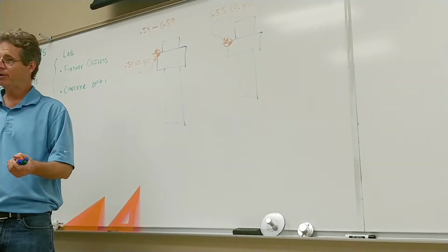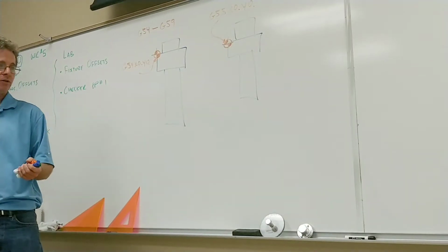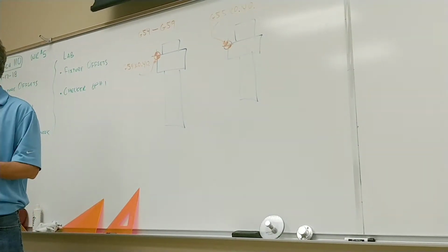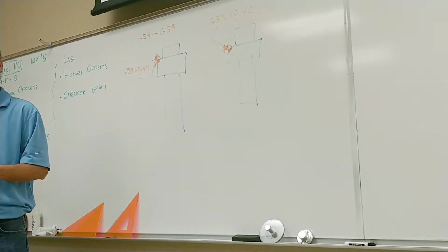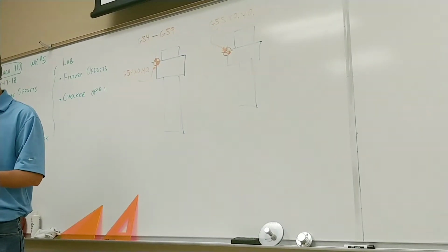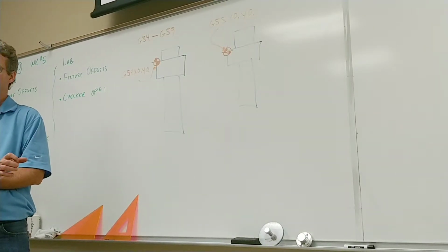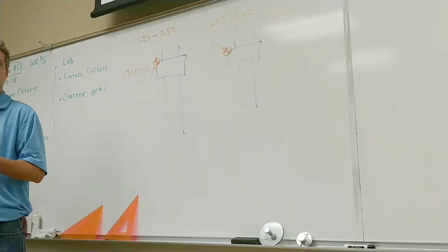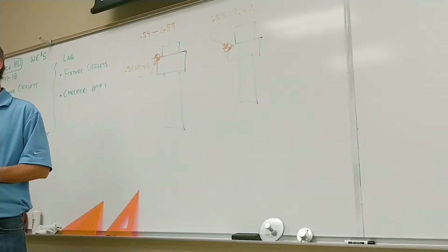Well, the material. When you buy material, for example, any extruded material, aluminum, cold rolled steel, whatever you're getting, that material has a tolerance. And actually, as you measure the width of your material from one end of the bar to the middle of the bar to the end of the bar, and then maybe a bar that came towards a later part of the lot when they made it, it's going to be a bit different.